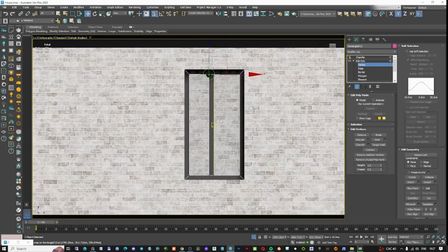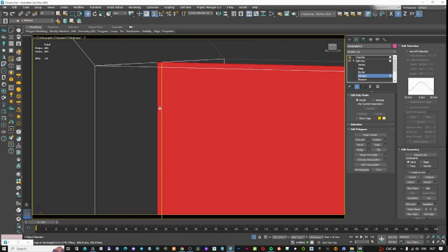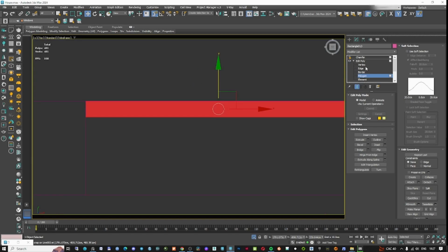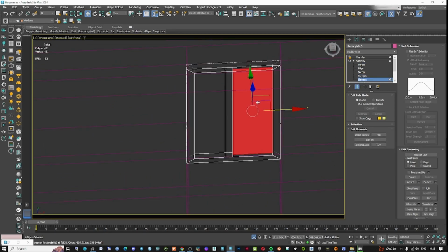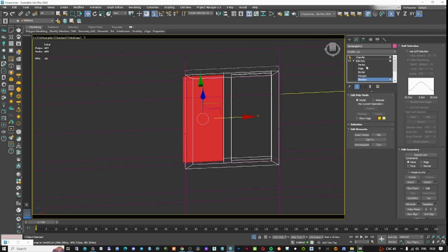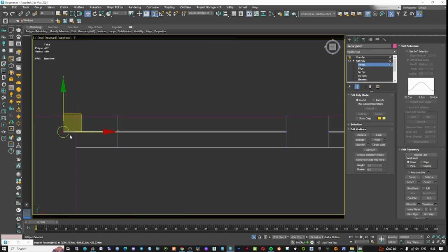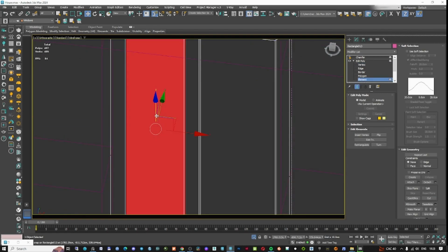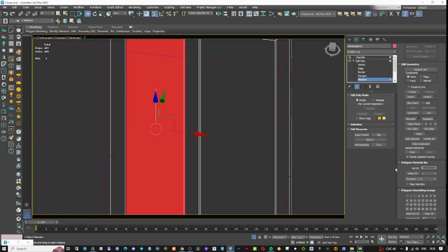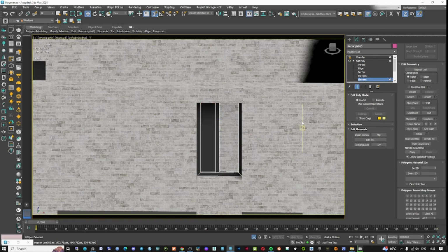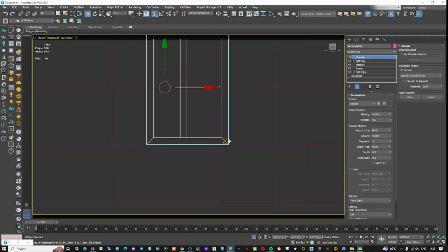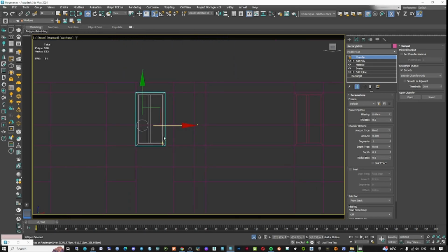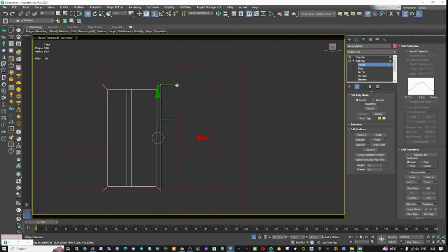And for the window, I'm just going to move the polygons from the left side, also in the middle, and make a copy of the glass sheet that I have, and change the material of it by changing the material ID, because now my window is composed of two materials with two different IDs, one dark and one transparent, so it's quite easy to do that. After that, I'm just going to make copies of these windows everywhere on the first floor.